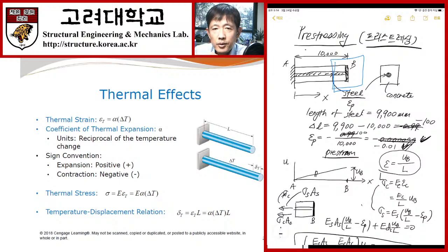And another subject that we discussed today is non-mechanical strain. Okay, non-mechanical strain. Here, the key point to understand non-mechanical strain is that Hooke's law is only for the strain caused by the stress. So we can define the material behavior for the pair of stress and strain, especially strain caused by the stress.